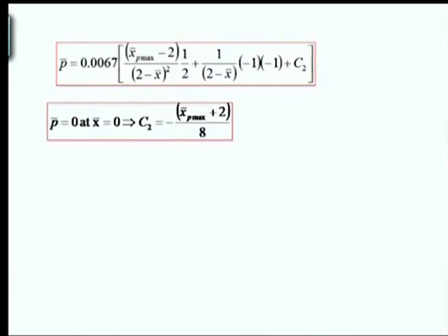We can find it out by some boundary condition. Similarly, we have another constant C2 which is also not known to us, so that also can be determined by a pressure boundary condition. That means we require 2 pressure boundary conditions, and we know that at the entrance and exit the pressure will be 0. So, we have the 2 boundary conditions we require, and there is a definite solution.